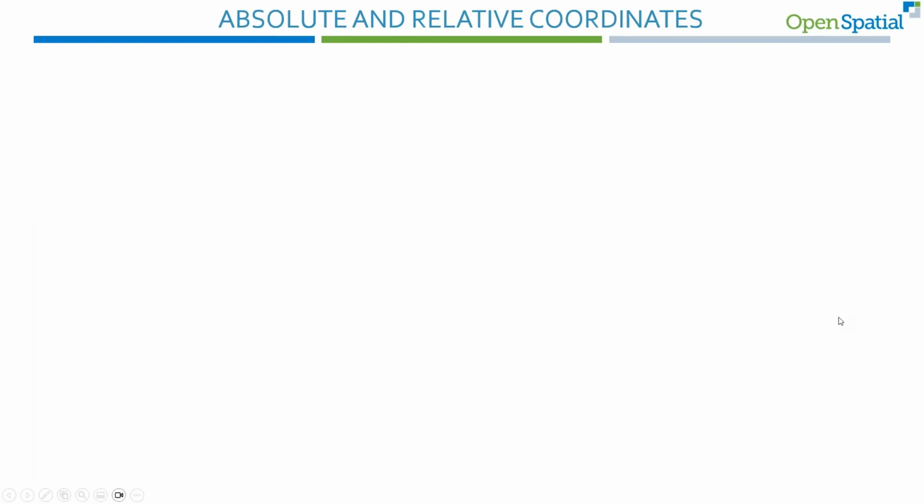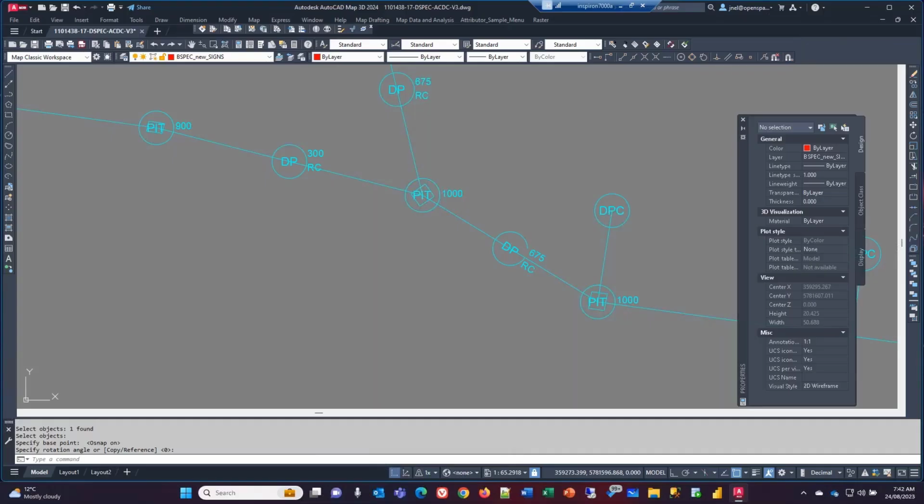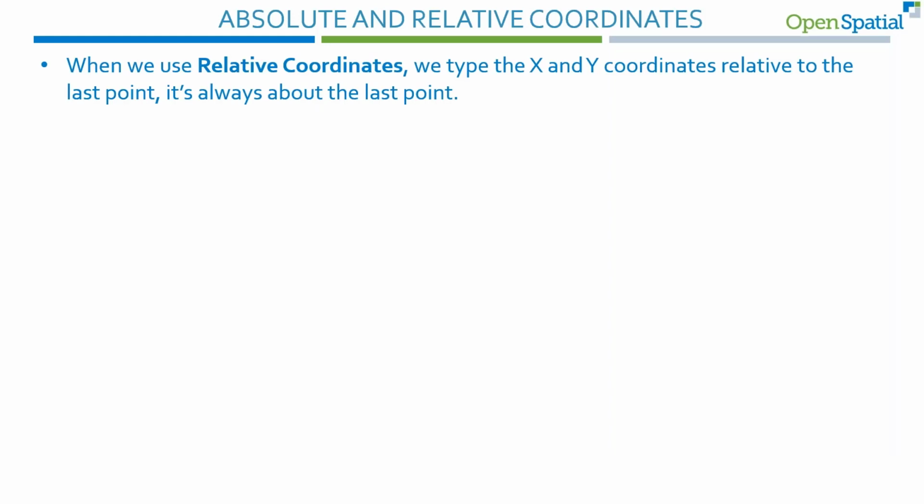Now, one of the things also within AutoCAD is your absolute and relative coordinates. Typically in the GIS sense, you use absolute coordinates. But if you're drawing things like a dash, etc., or something is being surveyed, you know, well, okay, here's my absolute coordinate, but this boundary is now 20 meters, 40, 50 feet long, and what is the angle? And so you can pick up all of those things.